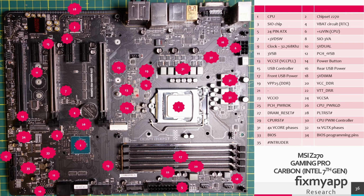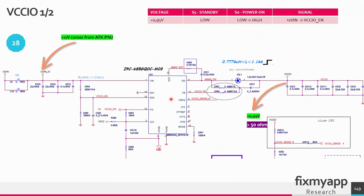In region 23, the VCCIO CPU voltage is created. In region 28, this is the buck controller. It will create 0.95 volt that will go to the CPU. And the CPU voltage rail is called VCCIO. VCCIO is a voltage of 0.9 volt. In a standby state, this voltage is not present. And in the power on state, it will go from 0 volts up to 0.95 volts.